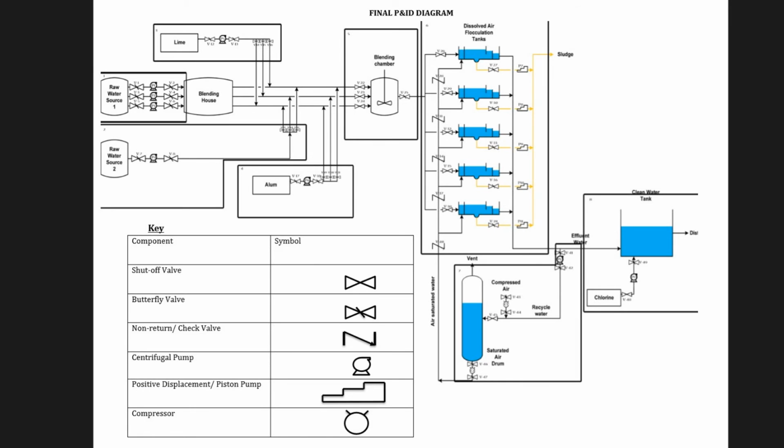A piping and instrumentation diagram is a diagram that shows the connection between the equipment in a process, as well as the equipment and instrumentation used to control the process. In the engineering profession, a standard set of symbols is used to prepare drawings of a wide variety of processes. The instrument symbols used in these drawings are generally based on an International Society of Automation standard.